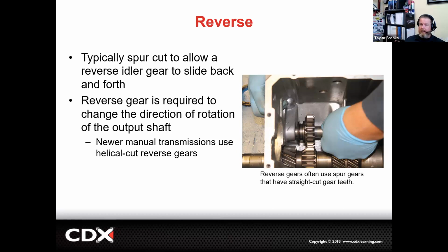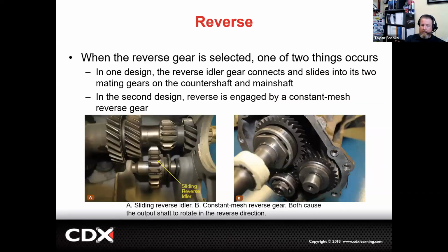I have an example of that here on my 3-speed. First gear is a non-synchronized gear, and you're actually moving it into place. It will ride on its own shaft with its own set of trundle bearings to support it, but we're not including that as a shaft because it's a little bit separate. In some cases, the reverse gear can be a part of the synchronizer hub for first-second, which we will have on the S40 Honda transmissions that you're going to be taking apart. But more atypically, we're going to have the reverse slider being separate, and that being a very low ratio.